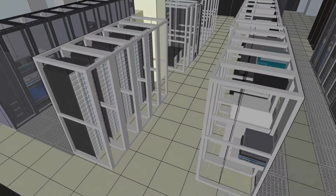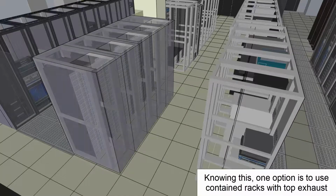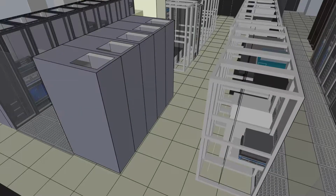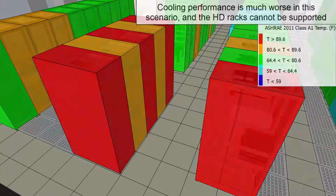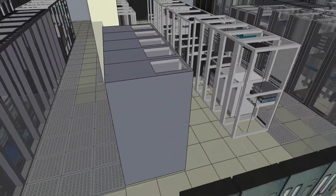the heat it dissipates. Knowing this, we can switch from open frame racks to self-contained racks with top vent exhaust. By running another simulation, we see that cooling performance plummets. The HD racks cannot be supported in this configuration. However, it can be helpful to understand why the deployment doesn't work.